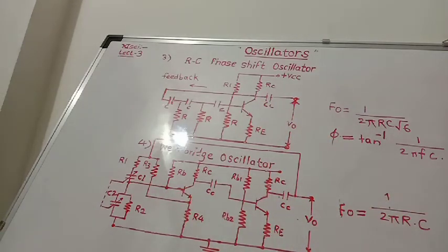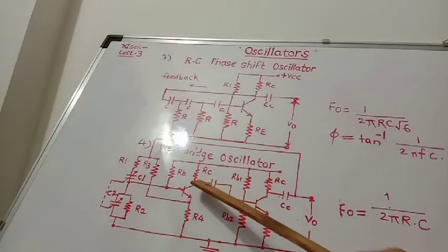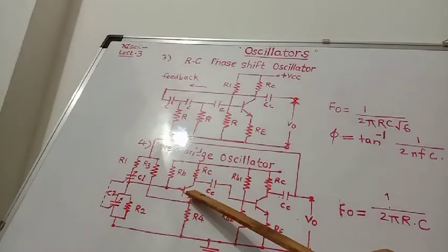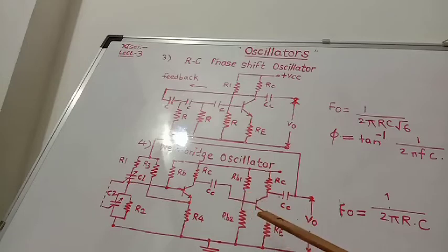As each amplifier stage provides a phase shift of 180 degrees, the first amplifier provides a 180 degree phase shift, and the other amplifier stage again provides 180 degrees. Therefore the total phase shift becomes 360 degrees, or 0 degrees. The phase shift through the coupling network is 0.